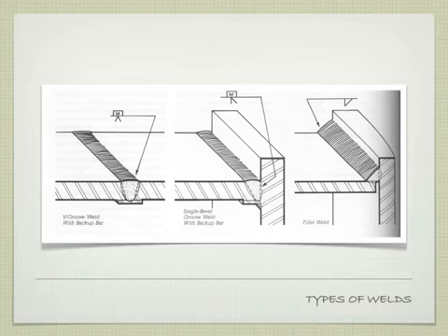If we look at something like this, it's a V on one side, we're welding to a vertical piece here and a horizontal piece here, right? This is doing the same thing. It's penetrating all the way through the depth of this material. So it would be a full penetration weld.